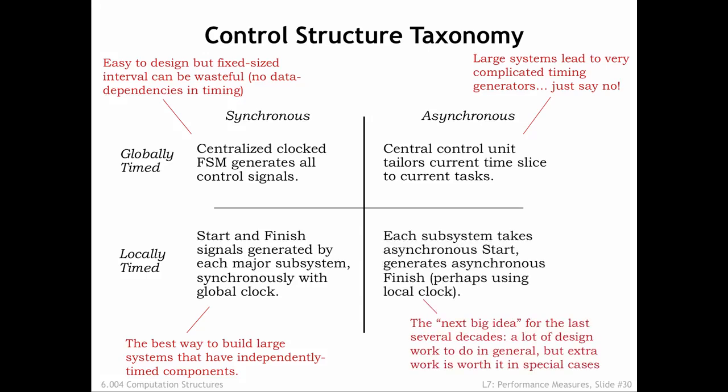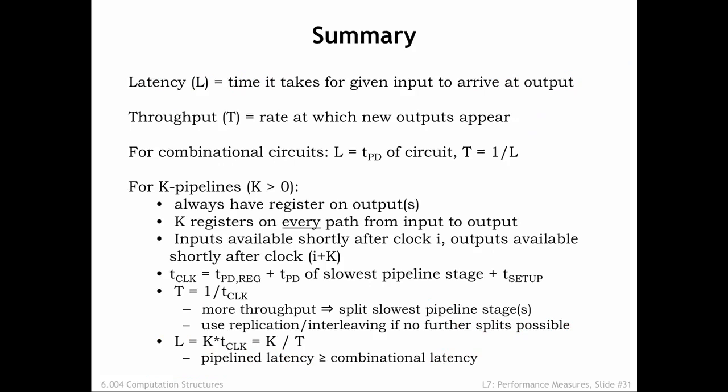But what about locally timed asynchronous systems like the example we just saw? Each generation of engineers has heard the siren call of asynchronous logic. Sadly, it usually proves too hard to produce a provably reliable design for a large system, say a modern computer. But there are special cases, such as the logic for integer division, where the data-dependent speedups make the extra work worthwhile. We characterize the performance of our systems by measuring their latency and throughput.